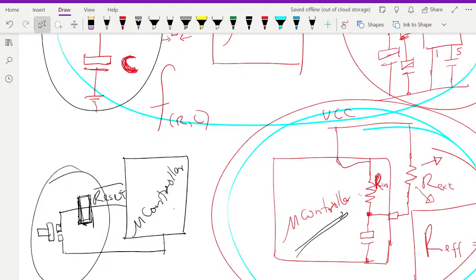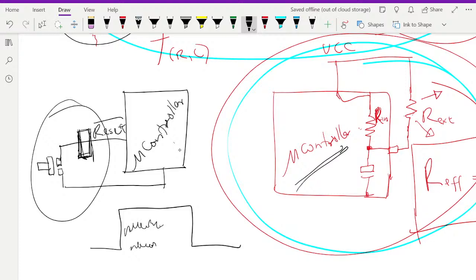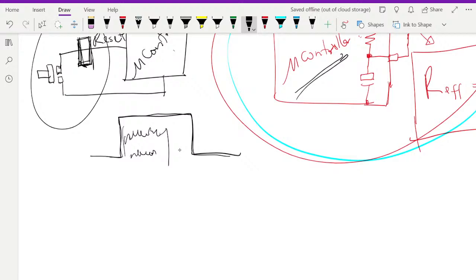With a 555 timer, the monostable period should be determined such that it's longer than your debounce period. So even if there's any jitter occurring within your system, it should finish within the monostable period, and the system only notices one period like that. Again, you can invert this. Just because it's high going doesn't mean that it's always high going.